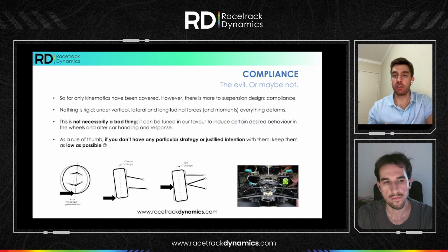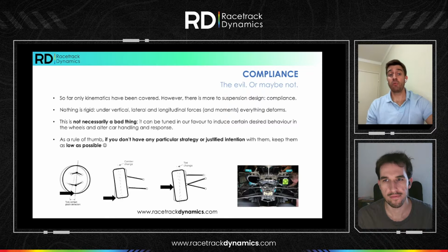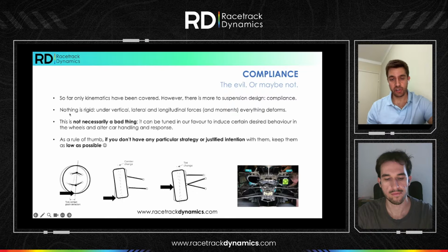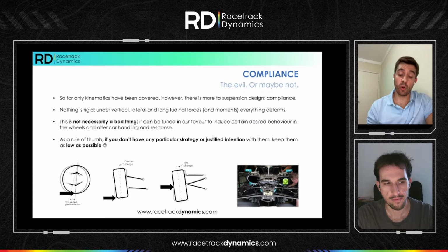So far, we are only talking about kinematics. We haven't discussed compliance, which is the evil, as always repeated by many gurus. Well, maybe they are compliant, maybe they are evil, but maybe they are not. We need to understand that it's quite obvious that under vertical, lateral, longitudinal load, everything is going to deform, and that's fine. It's whether we understand what is happening, and how we can overcome that, or even use it in our favor, which makes compliance the evil, or doesn't make it the evil.